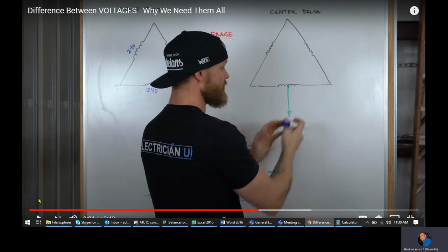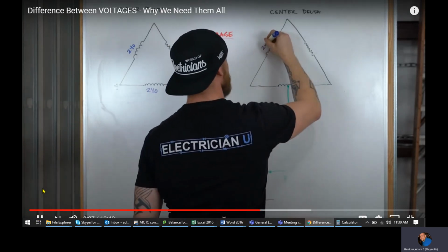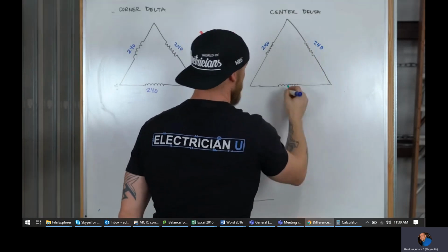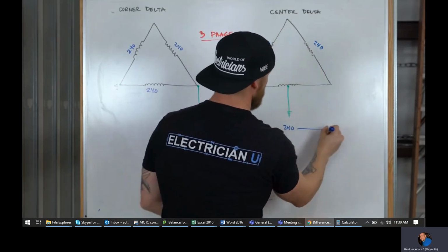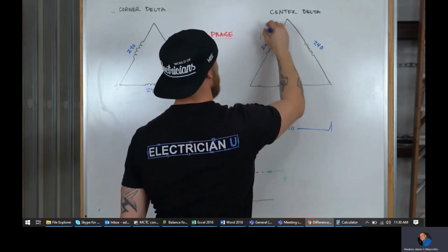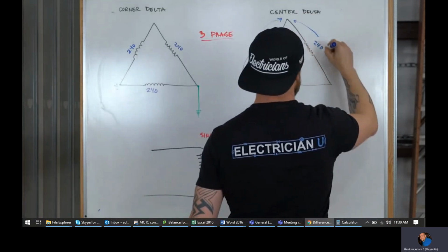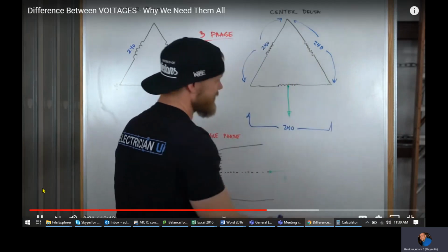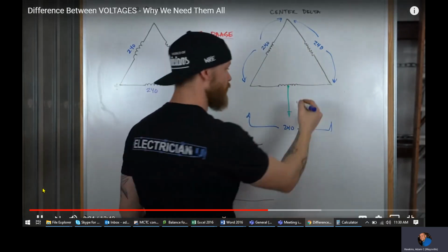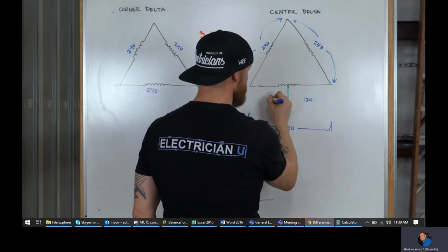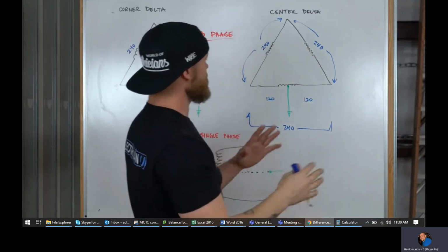And notice, guys, this is just how it's done internally, by the people who are making the transformers or designing the system. So we're dealing with the byproducts of this, but it's good to know how we're getting what we're getting. This isn't changing the potential. So you're still going to have 240 volts across all of your coils, 240 between there and there, there and there, there and there. But because we basically cut that coil in half, or intercepted the halfway point of it, it allows us to get 120 volts out of each side. So this is really common. You're going to see this.